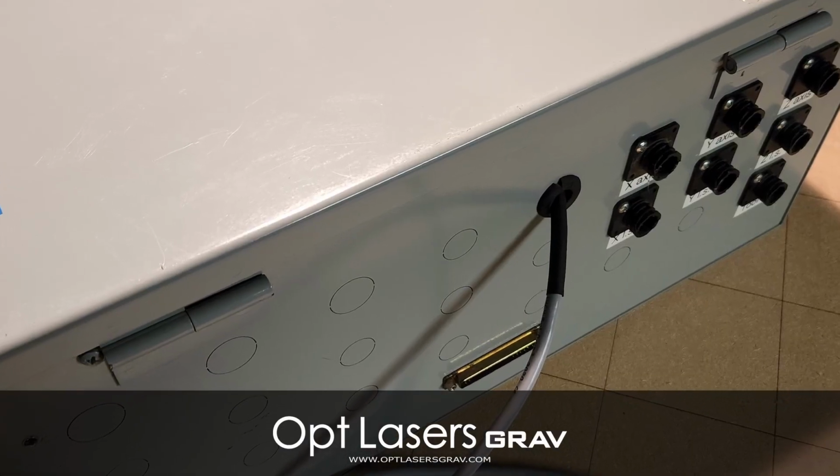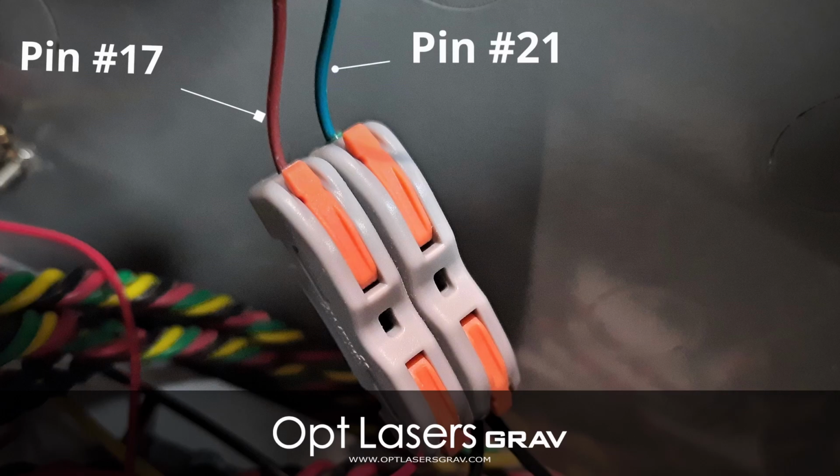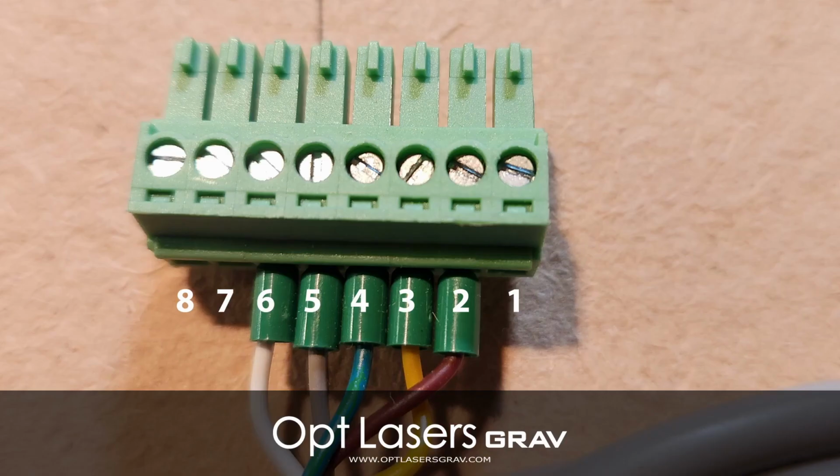Run the free end of this wire through the side of the control box. Using the lever locks, connect the brown wire to position number 17, the pin just installed, and a green wire to position number 21. Now on the other end of the wire, connect the 8-pin connector. The connector should be wired like this.